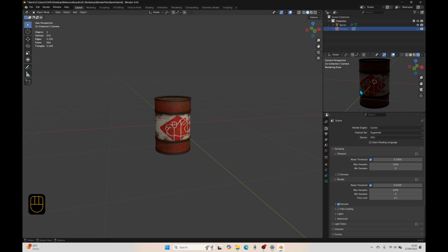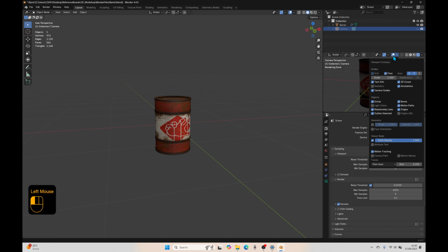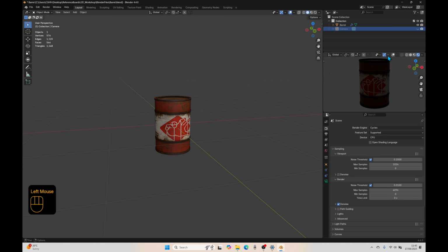And the last thing I want to set up in here is just turn off all these gubbins that we've got hanging around. So we don't need the Cartesian coordinates, we don't need this just here. So we can come up and click viewport overlays and turn that off. And then just to the left of it, show gizmo, we can turn that off as well. And you can see now we've got a nice clean image, and this will start to update. Once we add lights and we add in a mesh underneath like a floor plane, this will start to really